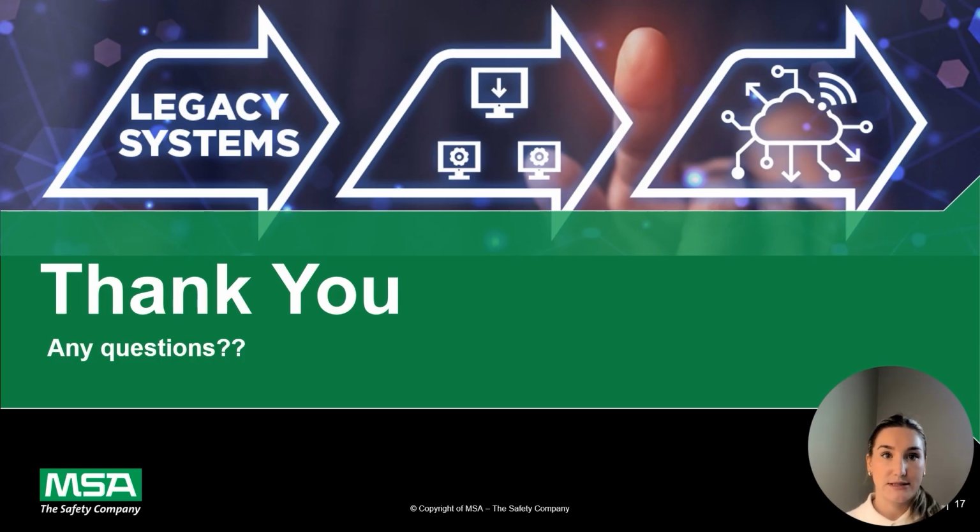For mission critical systems, the best practices would probably be segmentation. Keep Modbus devices isolated from other networks, not on the enterprise LAN. Use gateways that have secure encapsulation, TLS certificates, tunneling, etc. You want to always have a fallback path or duplicate gateways to avoid a single point of failure. And then watch out for unusual traffic too. Modbus can't stop an intrusion, but it can detect it at the network level. So while Modbus isn't inherently secure, a properly designed architecture can absolutely make it safe enough for mission critical devices and reporting.